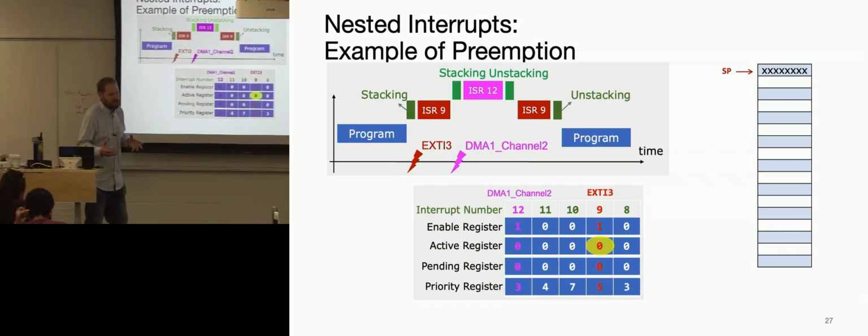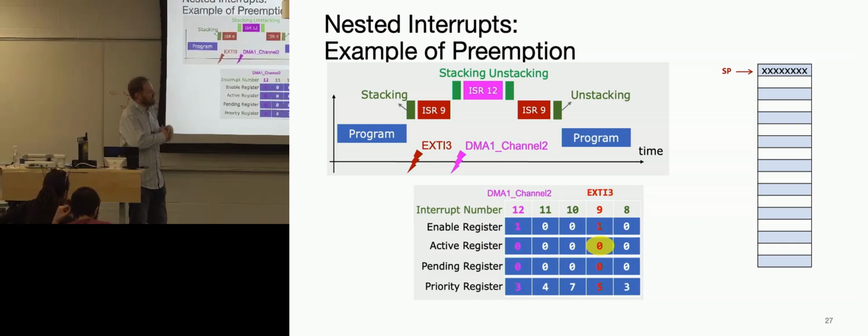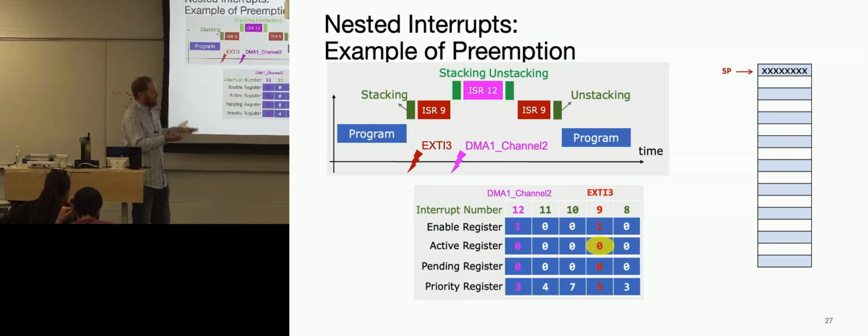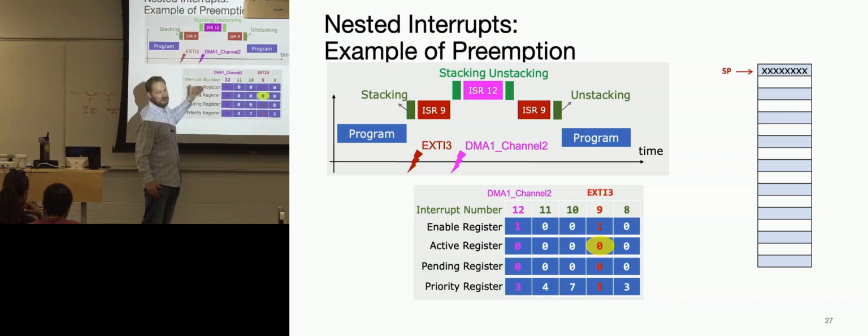When would that happen? That happens if you've configured a whole bunch of interrupts on your device and told the peripheral, when this event occurs, raise this IRQ pin, because that comes from the peripheral. It's not the NVIC that sets the signal going high or low. But the NVIC has a choice of listening to it or not.